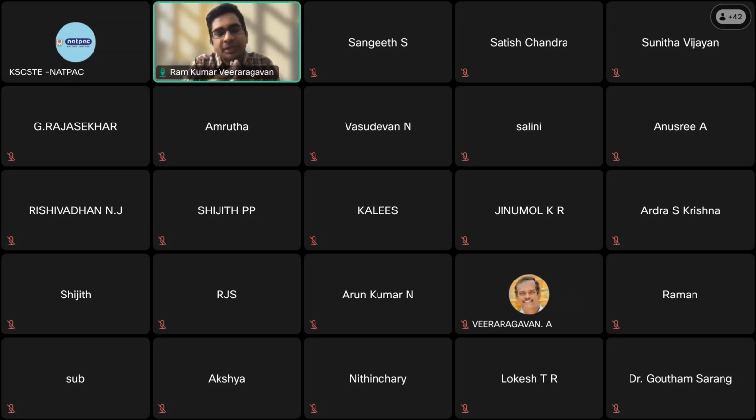Yeah, so IDEAL-CT is similar to our traditional tensile strength testing, except it evaluates the post-peak slope to evaluate the mixture stiffness. So it is ideal for Indian pavement condition, in terms of cost as well as time. Both the contractors and the state DOT agencies can have a minimum investment to evaluate the mixture performance. So it is feasible, and it's an appropriate test to consider for BMD implementation.